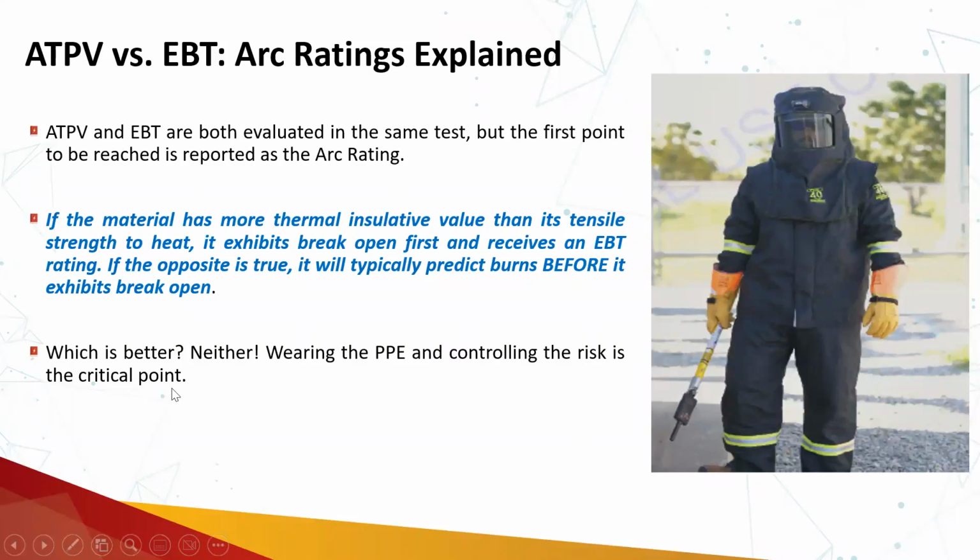So the question is which is better. If in an exam they ask whether you will select the personal protective equipment based on ATPV or EBT: being the end user, we don't care about ATPV or EBT, because for us the arc rating is important.